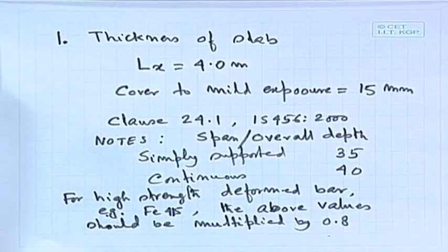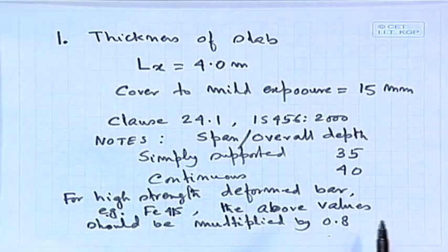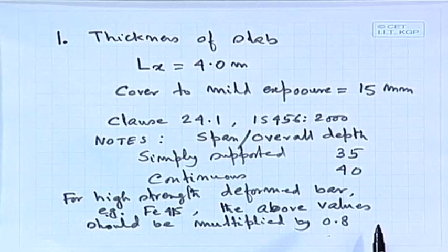So, page number 39, yes, and it further states that for slabs of shorter spans up to 3.5 meter with mild steel reinforcement, the span to overall depth ratios given below may generally be assumed to satisfy vertical deflection limits for loading class up to 3 kilonewton per square meter.